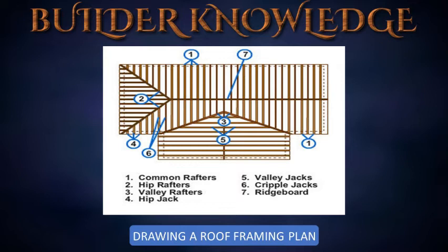Procedures for your sketch building outline. You must know the shape and dimensions of your building to be able to make a scaled drawing of the building. For your drawing, you will start with the front of the building at the bottom of the sheet. You will use the scale 1/4 inch equals 1 foot. Darken outline of building. Draw hip roof lines. Locate and draw center lines. Locate intersecting points for hip lines.